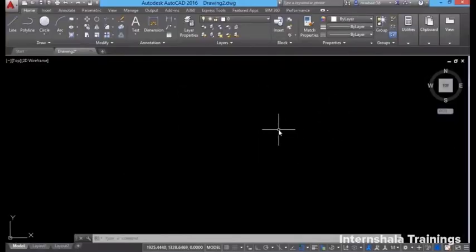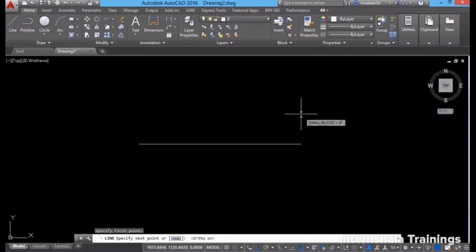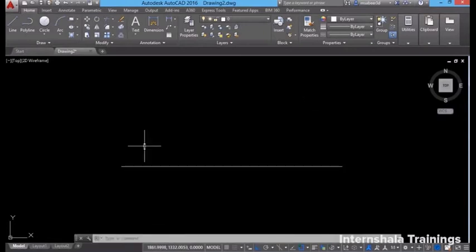You can also input distance in absolute values. I'll show you an example. I'll draw a line from this point and I'll turn the ortho mode on, with a length of 120 units. Next, I want to draw a line at a distance of 45 units from this endpoint and I want to give the distance in absolute values. So before drawing the line, you can bring the origin to this particular point. How do you do that? For that, I'll just click on this icon. It is called the World Coordinate System icon and that is a default coordinate setup in AutoCAD.